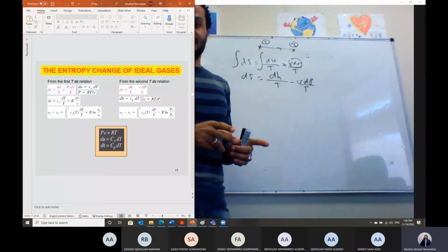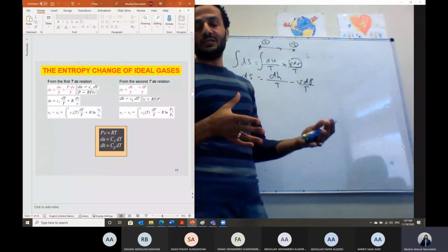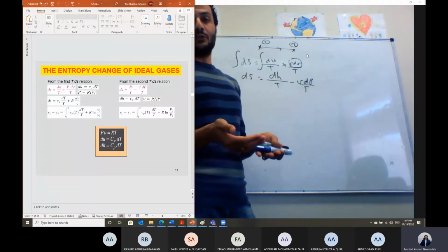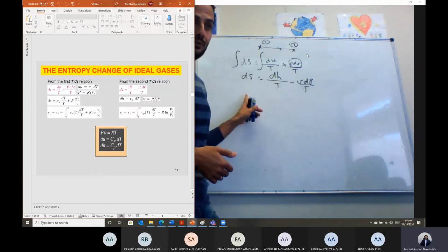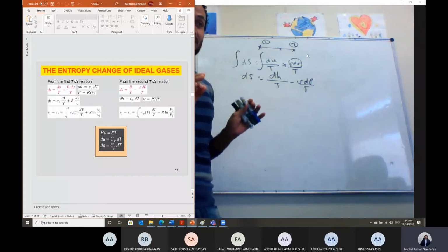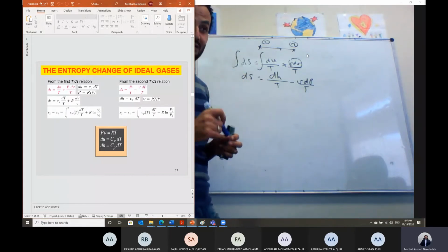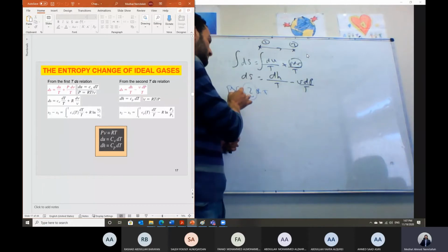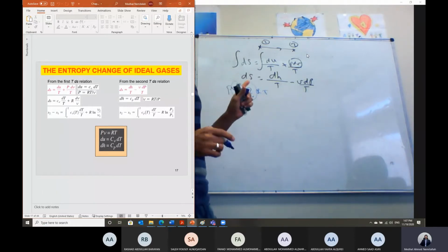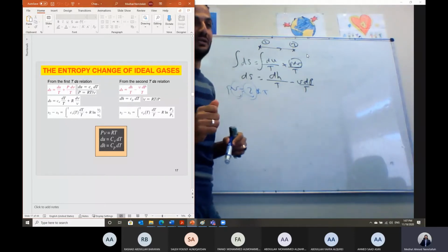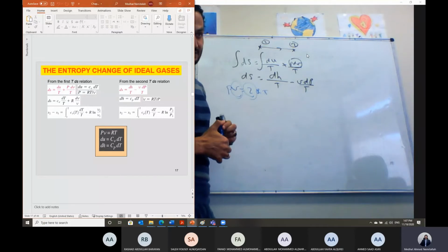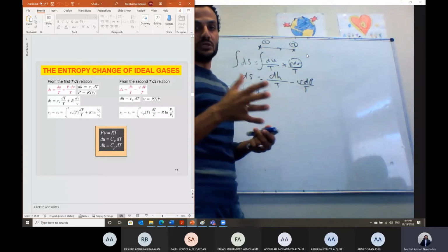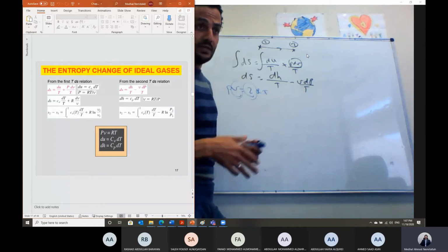if you use the ideal gas equation, PV equals RT, then you will be falsely calculating the actual volume of the gas. The actual volume may be higher, so you are selling a volume but actually giving a higher volume because your calculation is wrong. So when it comes to industry and you have to calculate the actual volume of a gas, I have to use PV equals ZRT, and I have to calculate the value of Z in order to get the actual volume. Because an error in industry is just transferred to money, you will be losing money. So if you have a small error in each gas cylinder, like propane or methane, which is used in houses for cooking or something.